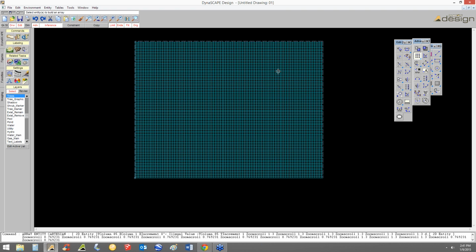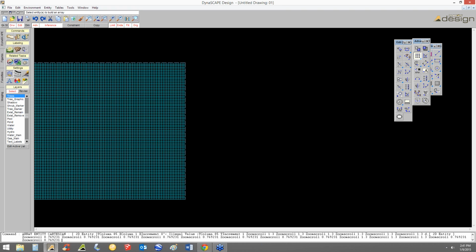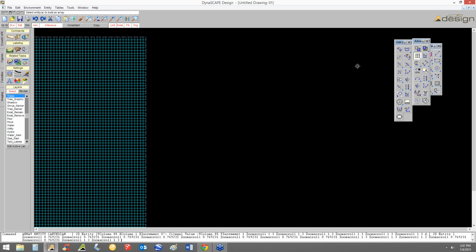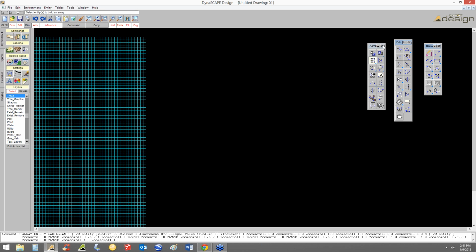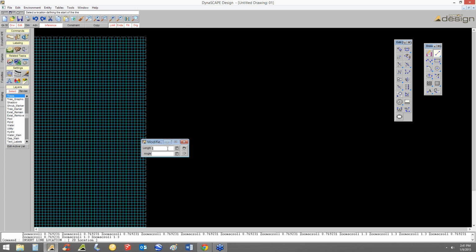So he's asking, if I want to make a 40-foot 7 and 5/8 line, how do I enter that into the dialog box? Okay, we go like this: 40-foot, 7, dash, 5, divided by 8, enter.